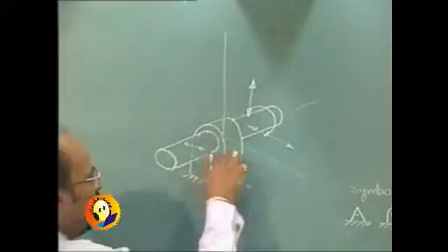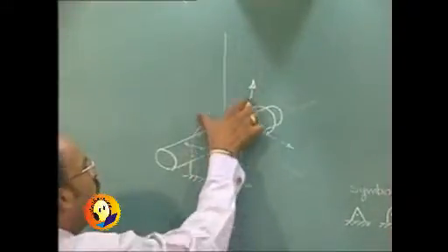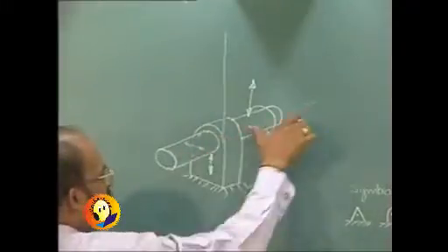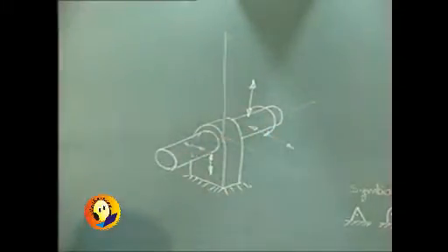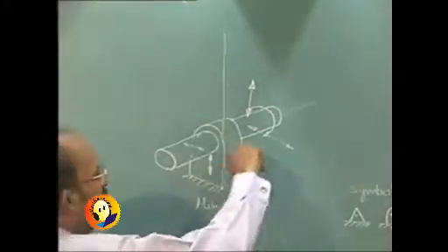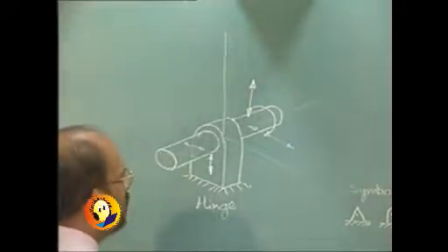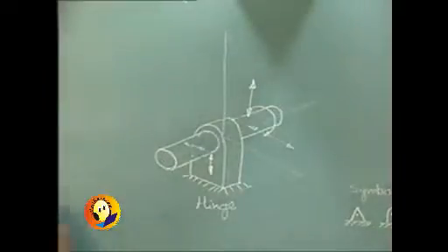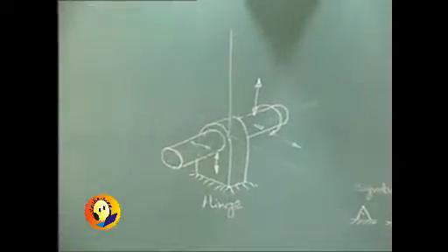We want to say that this particular shaft cannot be lifted up, lifted down or pulled in any other direction except this z direction. Now this support is called the hinge support. In other words, if I apply some moment to it, like this one, then the shaft can rotate. Another consideration, the hinge can be shown in this way.